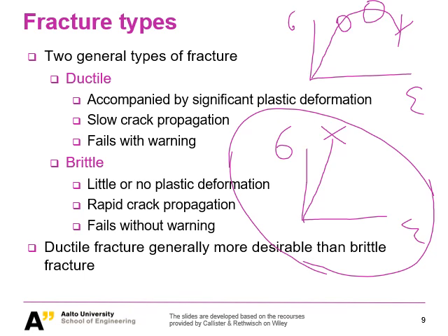Because locally, if you observe certain dislocations and certain atoms, there is always plastic deformation, even for brittle fracture. So identifying the fracture or damage mechanism for brittle fracture is even currently an active field. You should know this kind of statement is on a macroscopic level. And the second feature is rapid crack propagation. For example, ice breakdown is a type of brittle fracture for ice.